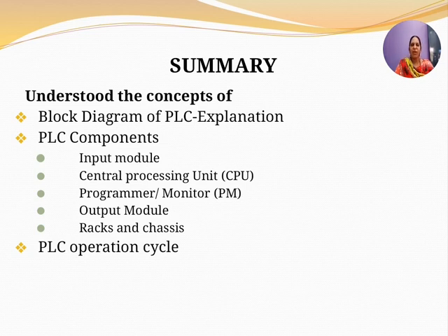The different basic units of the PLC section consist of the IO, input output section, the processor section, and the program loader or monitor section. The input section converts the field signals to logical level signals that the PLC processors can read directly. The processor section reads these inputs, processes the signals executing the program and prepares the output signals.